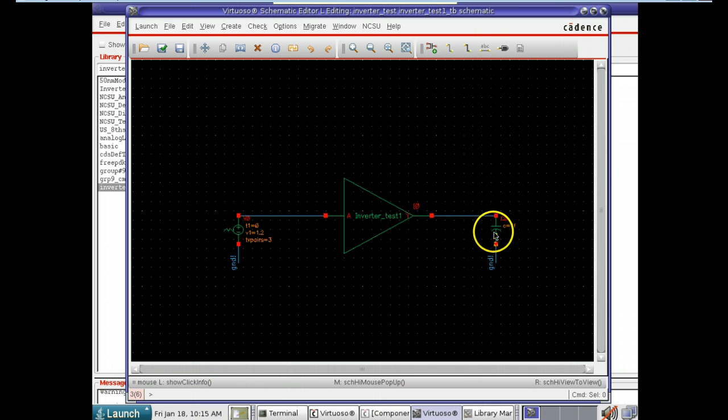the output. Once you guys get into lab 2, you're going to get into some of the fan out and whatnot. So when you get a fan out of 0, you're basically going to want to be using a capacitor equal to 0. I know that's a weird thought, but if you don't, you have an open node here and it won't allow you to simulate. So when you have a fan out of 0, you're basically just wanting to get what the output of the CMOS inverter is without any load connected to it.